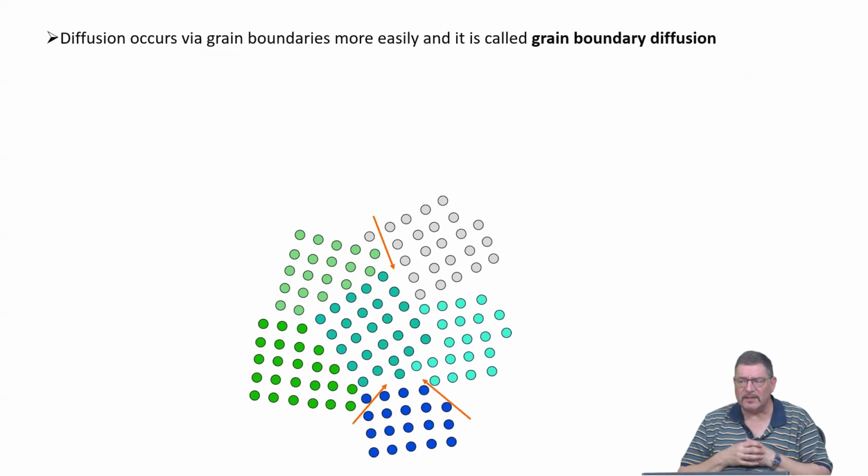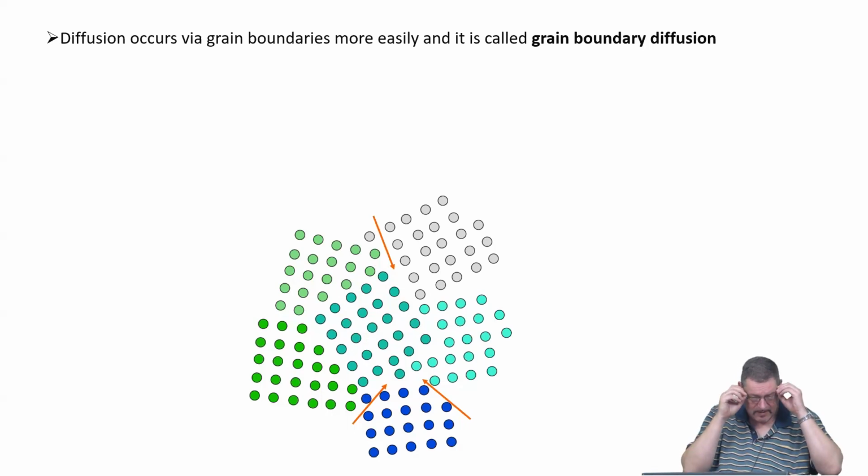Yeah, if we go to the next type of defect, then we go to grain boundaries. So from 1D dislocations to 2D grain boundaries, again a 2D representation. And again, the same argument holds, right? So if we have atoms situated in a grain boundary, then very often that grain boundary has an excess volume. So it means there are more options to accommodate jumps of an atom. The activation barriers will be lower.